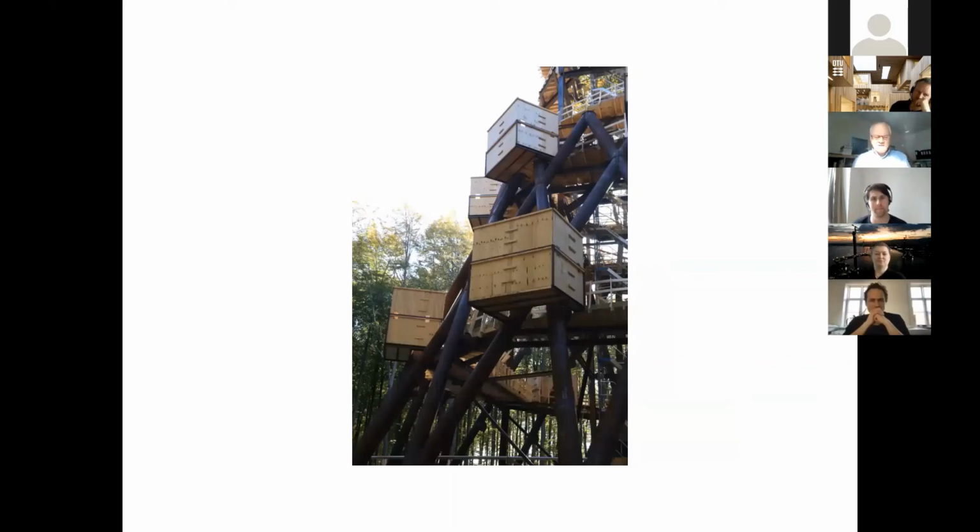In actual fact, the welds are simply fillet welds, but of course in a bigger size, and the welds differed in size. As a quick guess, almost one day to finalize one connection, not more than that. Even though there was a lot of welding, it was rather simple to weld. The company from Poland that fabricated the whole structure, all the elements, we also took to the site for the site welding, because they had the experience and the certification to weld this weathering steel.